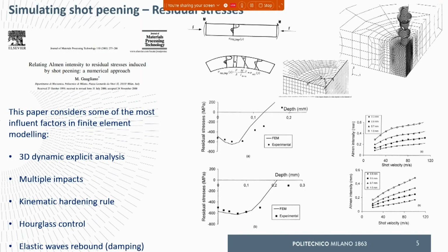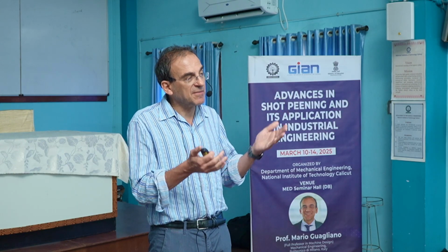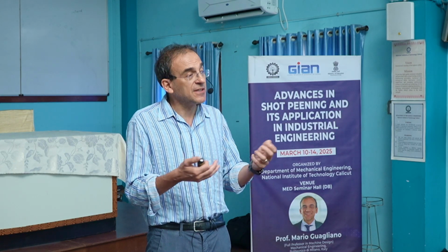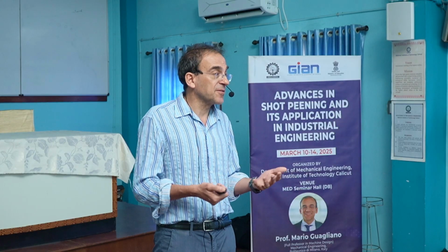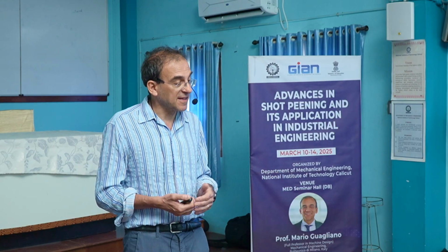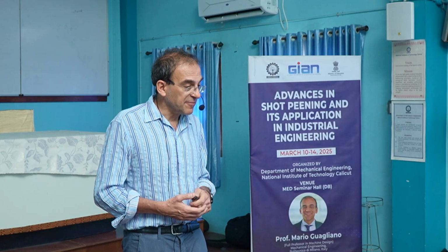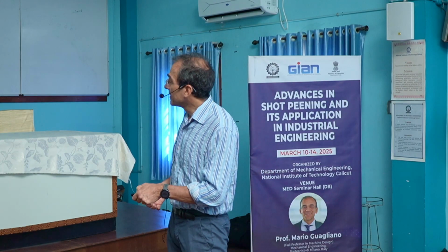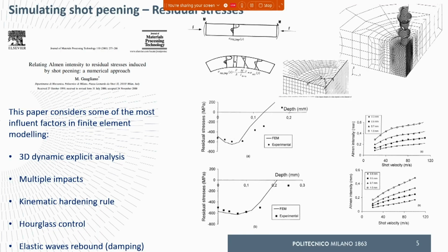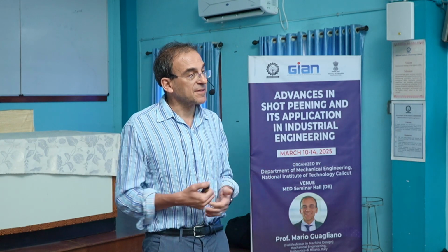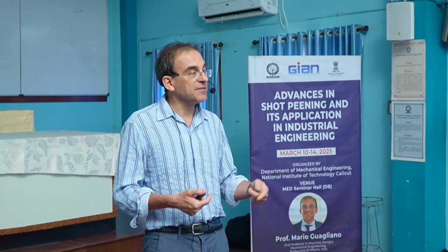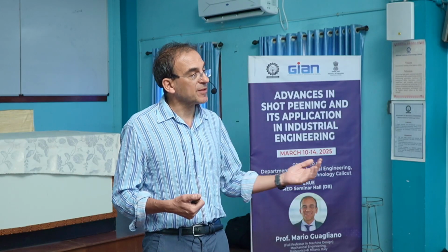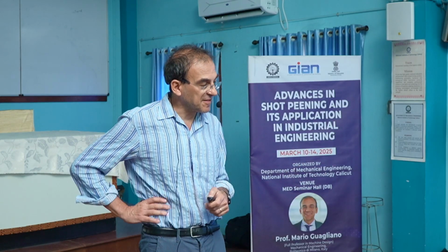What is the hourglass control? It's typical for finite element. Indeed, the finite element can have some fictitious deformation modes that are associated with zero energy. And so they are not real, but they can influence finally the result. And the hourglass control was also implemented. And the elastic wave rebound was also considered by introducing some infinite elements at the border of the model in such a way that the elastic waves coming from the consecutive impacts of the shot were not going to rebound and so were not going to influence the result themselves.